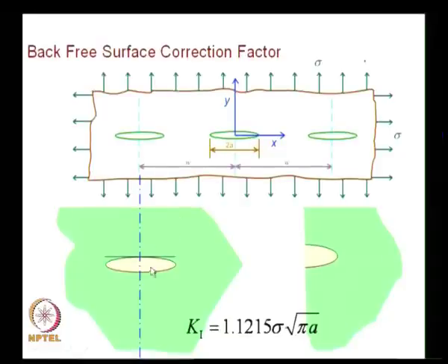What you will have to note here is, when you cut like this embedding the central crack, because of symmetry the slope will remain horizontal, but if I cut along the center of the crack, which is the case in a single edge notch specimen or double edge notch specimens, you will have a higher stress intensity factor and the crack will open up more.